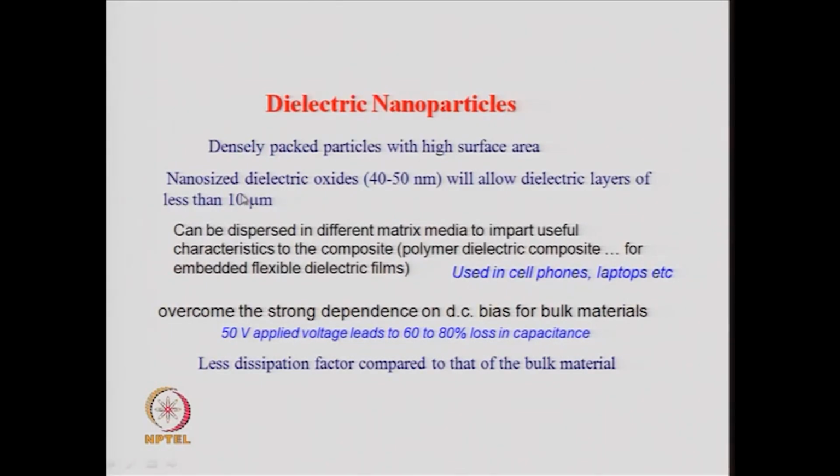Typically, if you can reduce these dielectric oxide nanoparticles to the size of 40 to 50 nanometers, then you can think of making dielectric layers of less than 10 micron, and that will be very advantageous in making the final size of the chip very small.